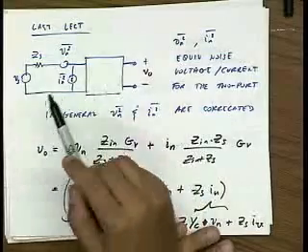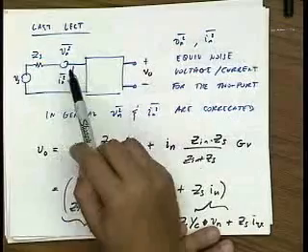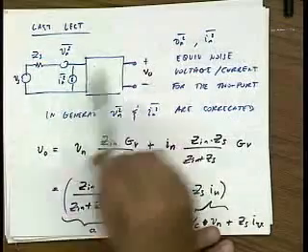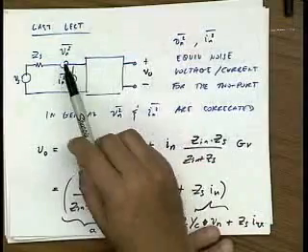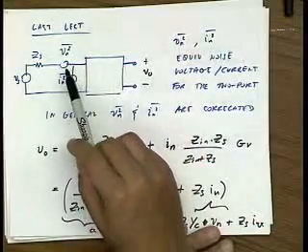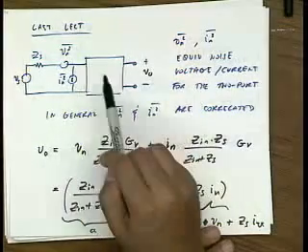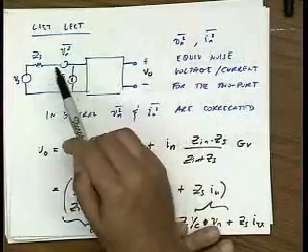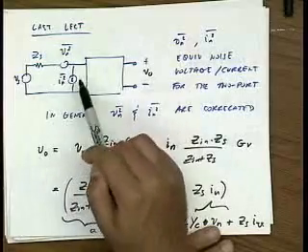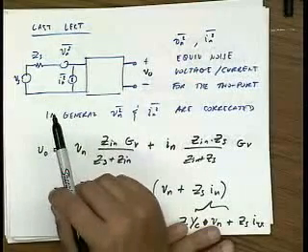Let's just for simplicity assume all these noise sources are independent from one another. When I calculate Vn, I also get some other superposition of all the noise sources inside of here, right? So therefore, it's clear that there are components of Vn which are correlated with In, right? Because they arise from the same noise sources. So I can split up Vn into parts that are just a constant times In, and a part that's completely independent from In, right?